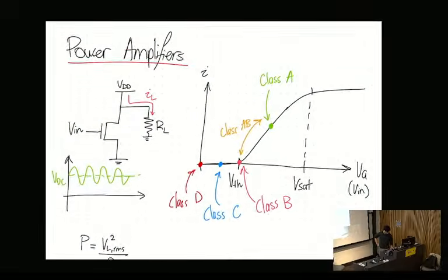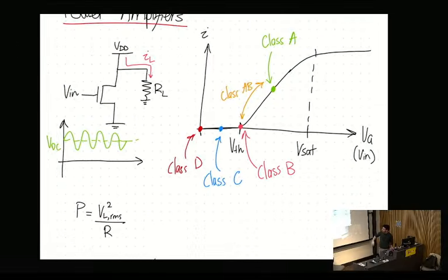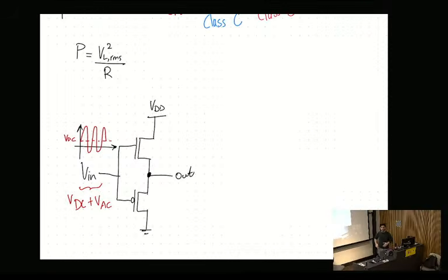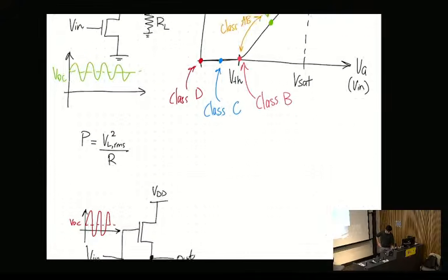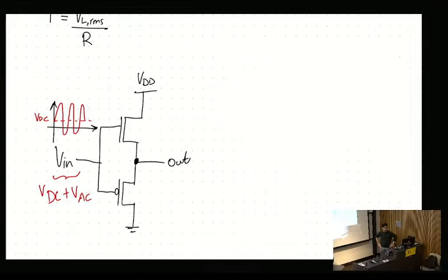Class A will work just fine with just that operation, that configuration there. But anything that is briefly off for any period of time needs both PMOS and NMOS, or for BJTs, PNP and NPN. For this one here, yep, this one.